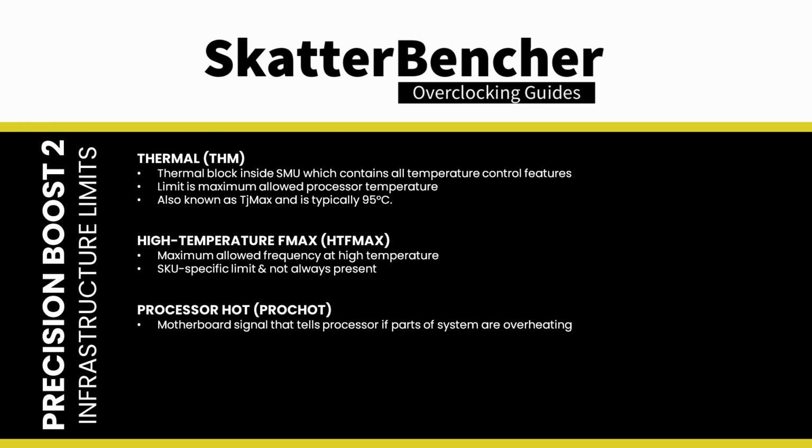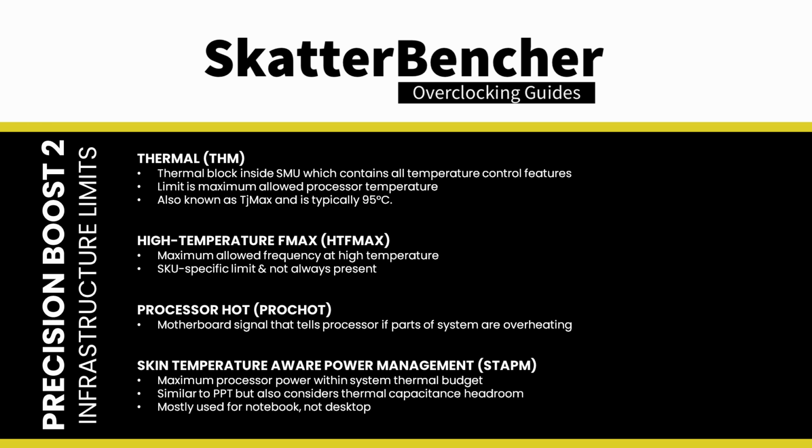Processor hot, or proc hot, is a signal within the motherboard design that tells the processor the other system elements are overheating and allows the processor to throttle performance. Skin Temperature Aware Power Management, or STAPM, represents the maximum power the processor can use within the thermal budget of the whole system. It is similar to the package power tracking, but also considers the system thermal capacitance headroom. It is primarily relevant for notebooks and not so much for desktop.